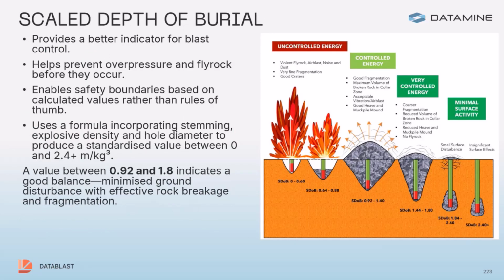Okay, now scale depth of burial. Scale depth of burial provides a better indicator of blast control. It's something that's been coming into the industry as a requirement for checking blast outcomes, and also as a regulatory requirement on plans. So we've recently produced a firing module in DataBlast which allows you to display scale depth of burial against the holes, so you can record what it should be, so that you can produce a regulatory document with plans if need be. Basically, it helps to prevent overpressure and fly rock before they occur.